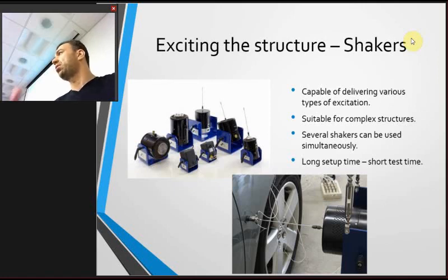If you have something of complicated 3D shape, you can excite it from different directions and with different force levels. The setup time is longer because, besides attaching the shaker to the structure, you also need to suspend the shaker from somewhere.